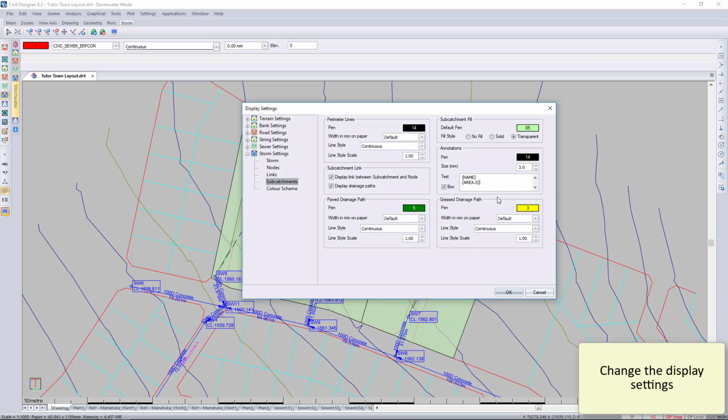I'm going to give it a name for displaying and the area in meters. You'll see there's a .0 there. That's to have 0 decimal places. So you can remove that. Replace it with 3 if you wish. This stage with stormwater, you don't need to be accurate to the 6 decimal place.